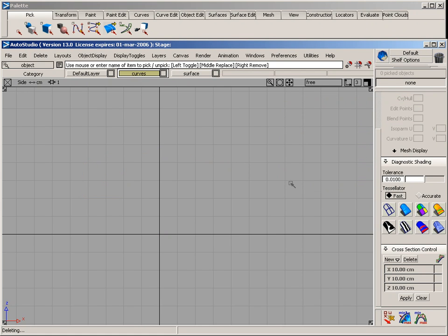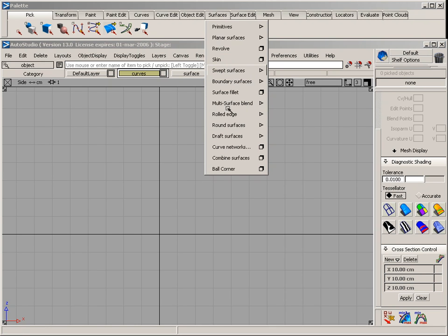In this next segment, I'm going to start using the flange tools to show you how to create part lines. The flange surfacing tools are located under rolled edge, fillet flange, tube flange, and tubular offset. Now, while these names are somewhat similar, maybe confusing, they have very useful, subtle differences in what they can do.